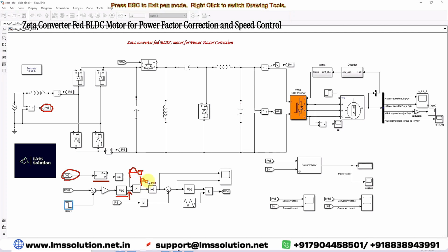After that, you have to use an absolute block. This absolute block converts the nature of the reference current to look like this. It's like a full wave rectifier output. This is now the reference current.